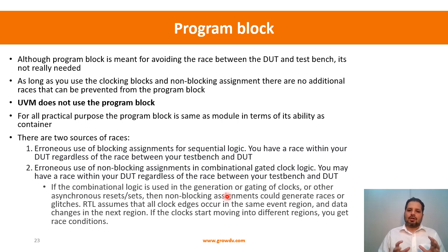Okay, so just remember, bottom line, the essential point that we are trying to communicate here is that as long as you use a clocking block and non-blocking assignments, there are no more races that a program block can help you prevent. That is the bottom line basic point that I want you to remember. Even if these other points that we are discussing here are not very clear, that is the main thing that I want you to remember.